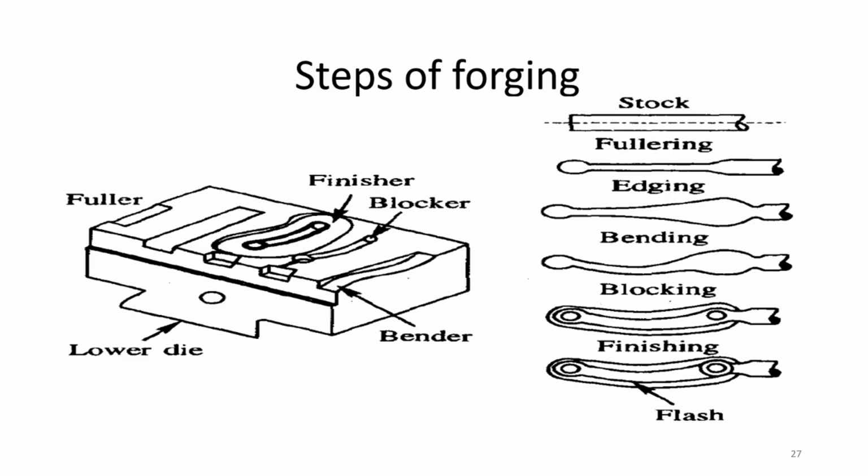No, but the liquid shrinkage will be compensated by the riser. For that particular part you don't provide any allowance in the pattern. The pattern will only take care of the solid shrinkage. Okay, so we don't need to consider the order for that volume shrinkage.